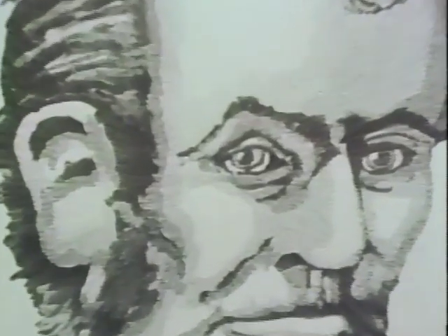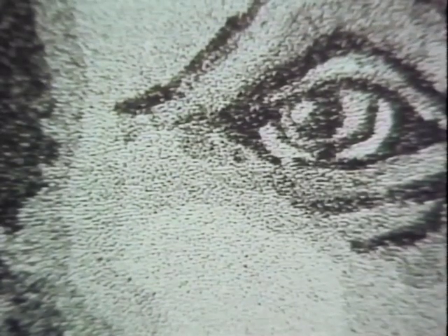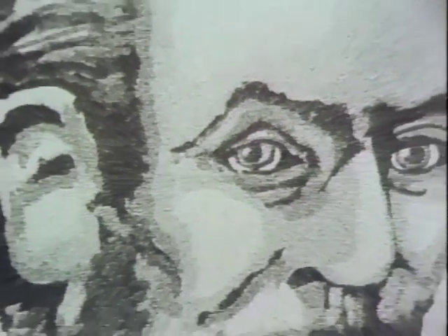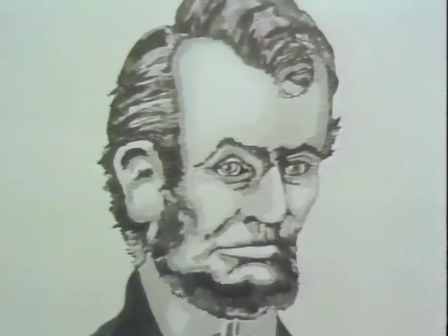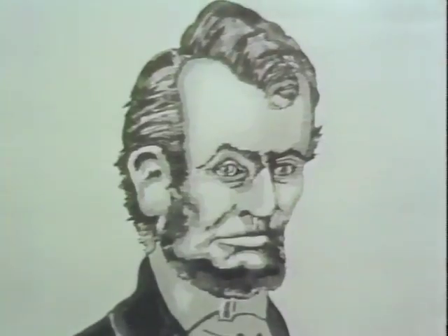To summarize then, we must break the picture into sections as small as possible to be able to distinguish or resolve the outline of the detail. And we must use enough levels of grey to be able to distinguish one detail from another by its relative brightness.